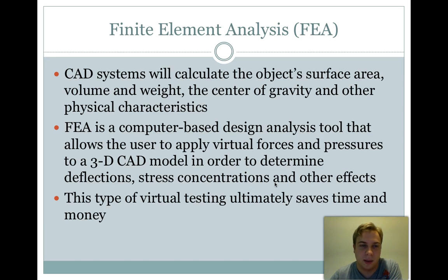Finite element analysis. CAD systems will calculate the object's surface area, volume, and weight, the center of gravity, and other physical characteristics. FEA is a computer-based design analysis tool that allows the user to apply virtual forces and pressures to a 3D CAD model in order to determine deflections, stress concentrations, and other effects. This type of virtual testing ultimately saves time and money.